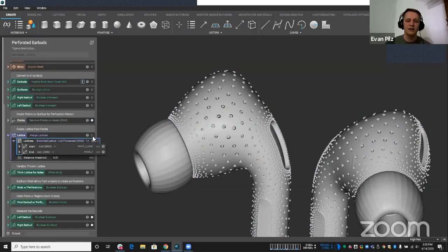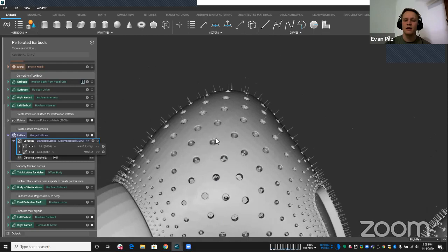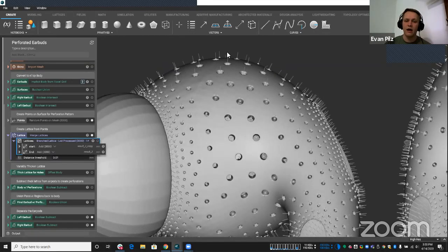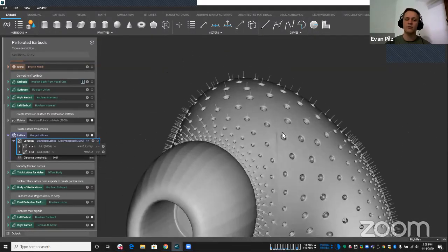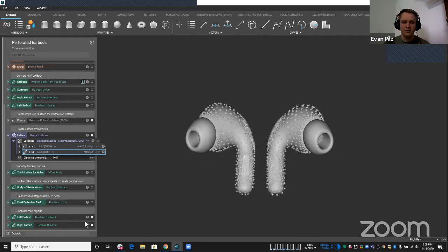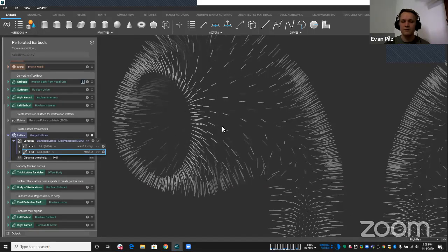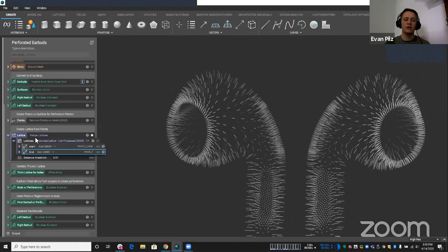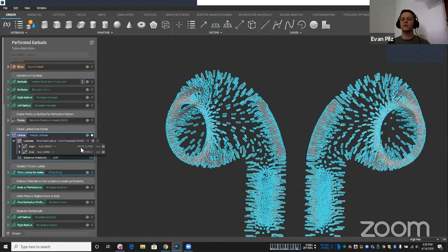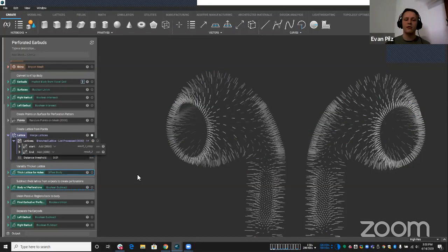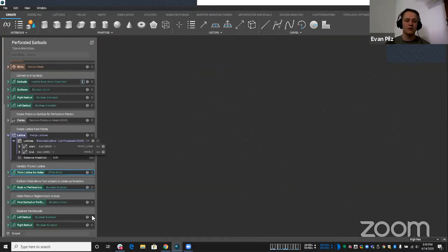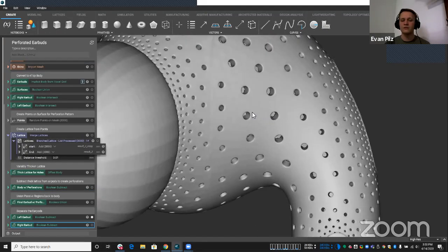So we're offsetting these points normal in direction, out and inside. So we have 2 points here, and we create a branch lattice between each of those 2 points. So you'll see we have this little list with a start and end point. We actually have 3,000 individual branch lattices that we created from these points. And when we combine these lattices into one singular one, we do a variable thicken. So that's how we did the variable sized holes here.